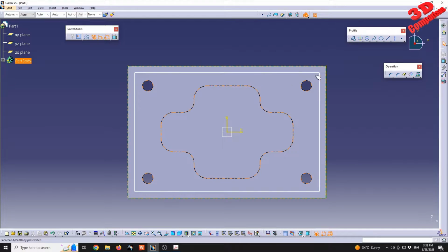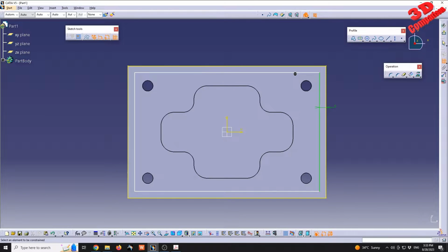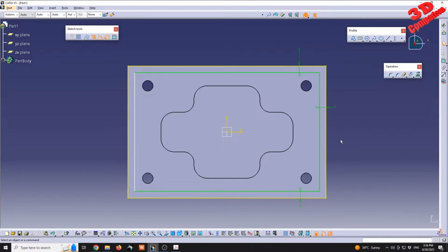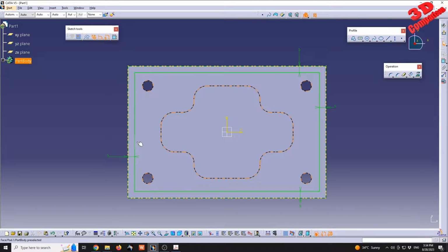So this will be the newly defined sketch. I can also come over here and add those values. So the lines will no longer be white, they will be green, that means that the software knows exactly where they are. And also we have that visually because the position didn't change during this operation.